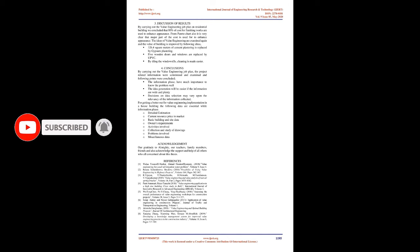3. Discussion of results. By carrying out the value engineering job plan on the residential building, we concluded that 80% of the cost for finishing works is used to enhance appearance. From the Pareto chart it is also very clear that the major part of the cost is used to enhance appearance. The ideas of value engineering are examined again and the value of the building is improved by the following ideas.